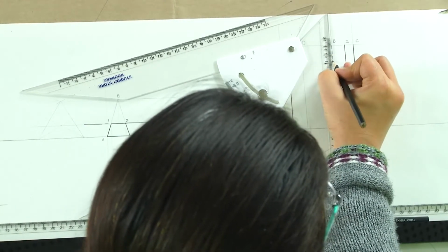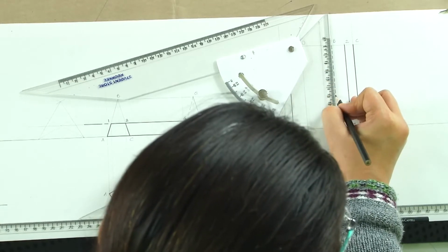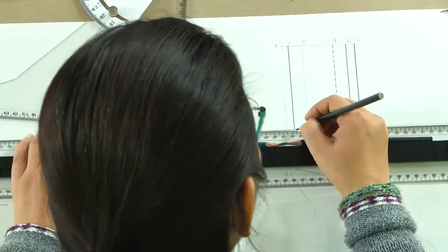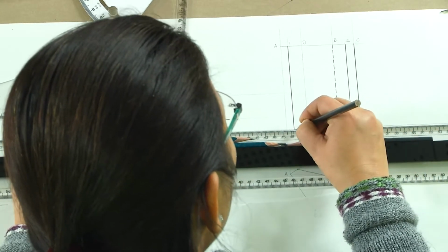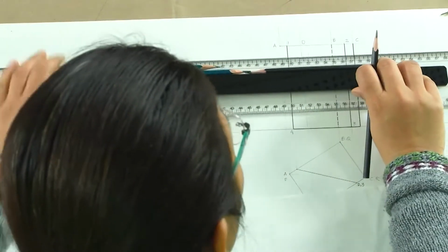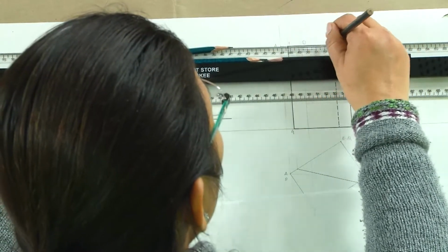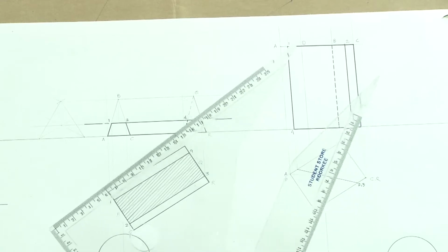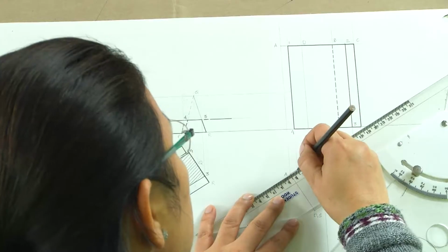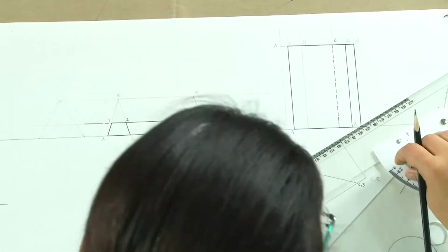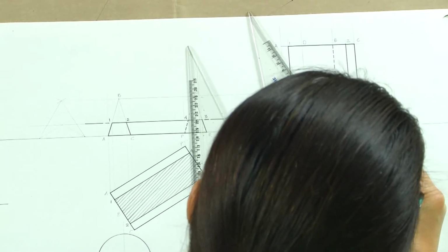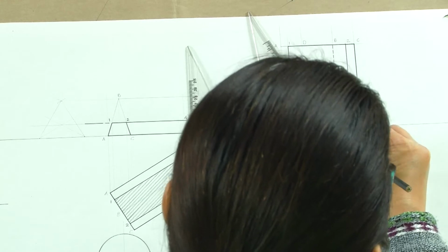So, what we have here is a hidden line which we see at the back. This is the final front view, front elevation of this rectangular prism, and this is the top view of the remaining part of this rectangular prism. So, it is not the original one, it is the remaining one. Now, one thing which you can see clearly is that the true shape of section is not visible here.